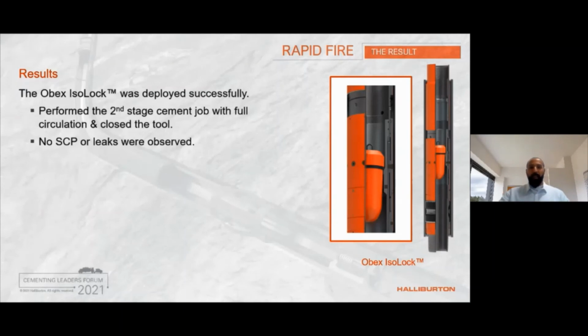The packer was set with planned pressure, opened the dedicated cementing ports, performed the second stage cement job with full fluid column, and closed the tool successfully. Also, no sustained casing pressure or leaks were reported by the customer after the job.